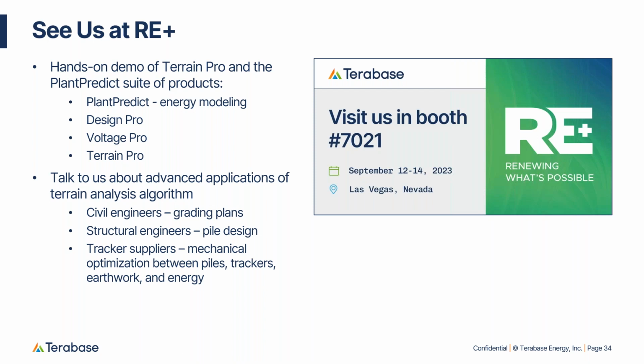Terrain Pro allows you to model different maximum torque tube axis slopes and solve for the resulting earthwork. East-west slope is currently not one of our design parameters, but this can be modeled with the results that come out of Terrain Pro. You can get finished grade elevations, top of pile elevations, and then you can model those to visualize the east-west slopes.